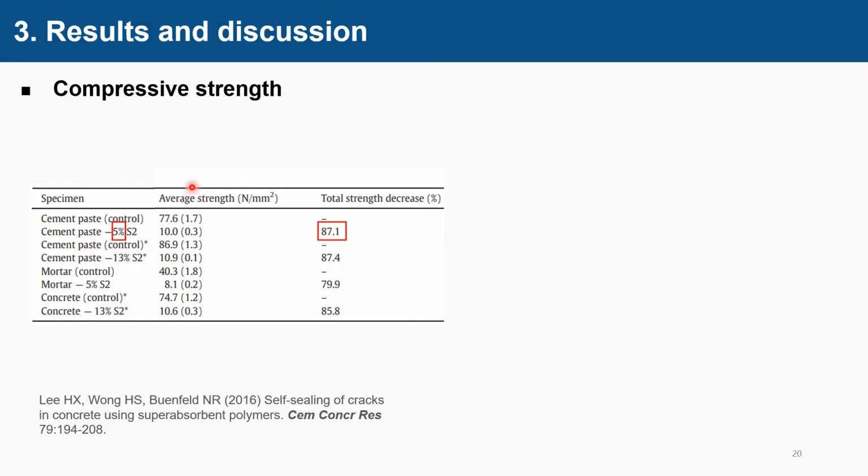Here we want to stress that the results I just showed are preliminary results. The results may vary a lot depending on parameters like void content, thickness of internal curing zone, and the extent to which the modulus increase caused by internal curing.